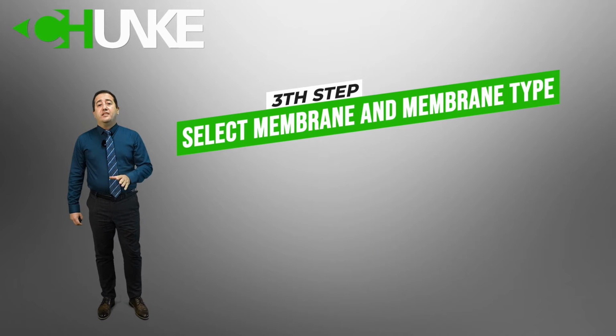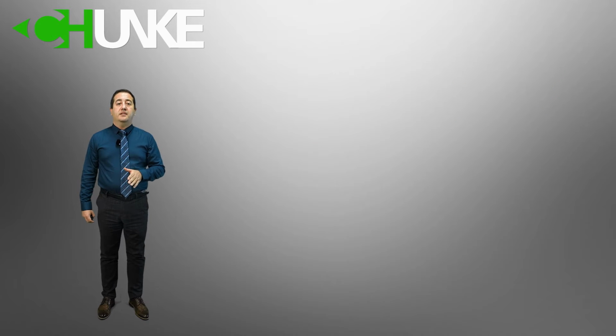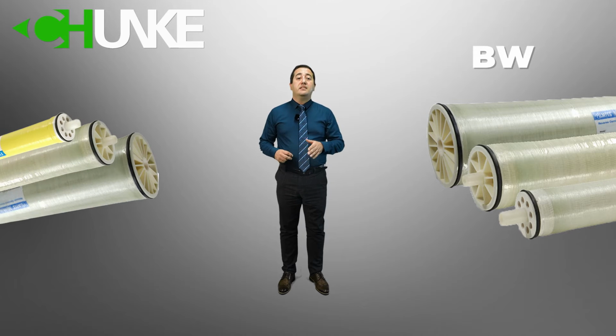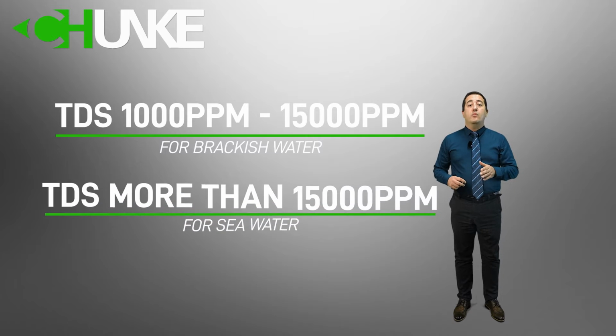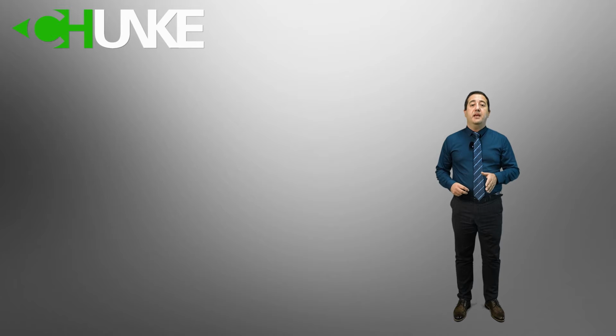Third, select membrane and membrane type. Elements are selected according to the feed water salinity, feed water fouling tendency, required rejection, and energy requirements. The first factor that has to be considered is the feed source. If the feed is brackish water, BW type RO membrane must be selected. If the feed is seawater, SW type RO membrane must be considered. TDS for brackish water is between 1000 to 15,000 milligram per liter, and in seawater is more than 15,000 milligram per liter. Meanwhile, milligram per liter and ppm are the same unit.